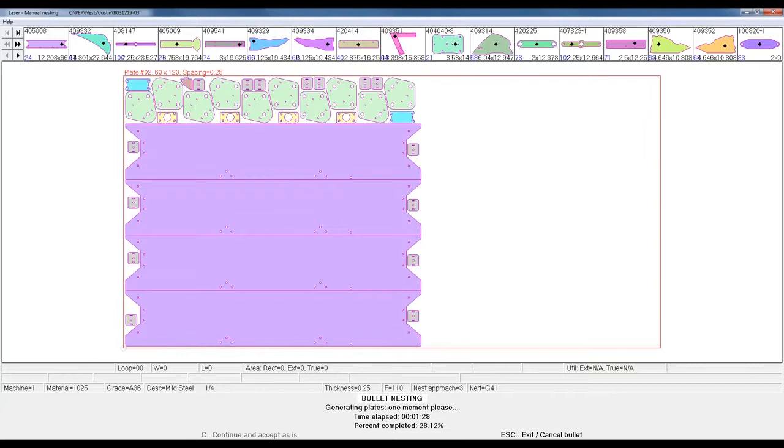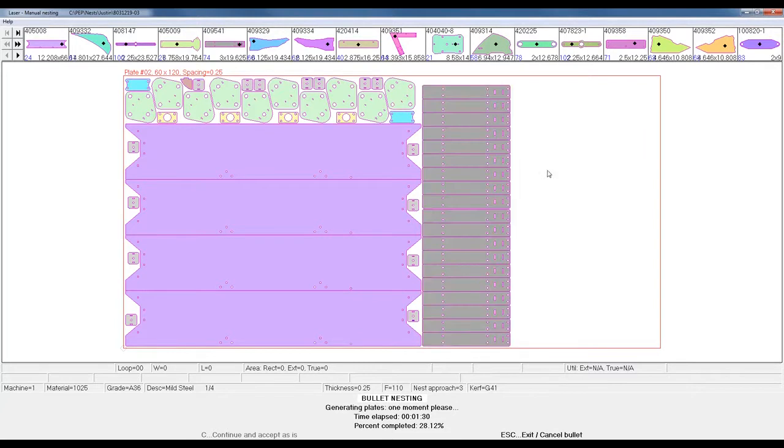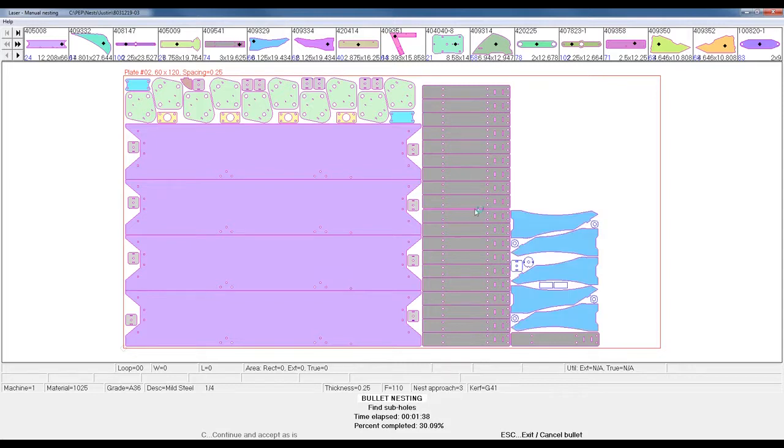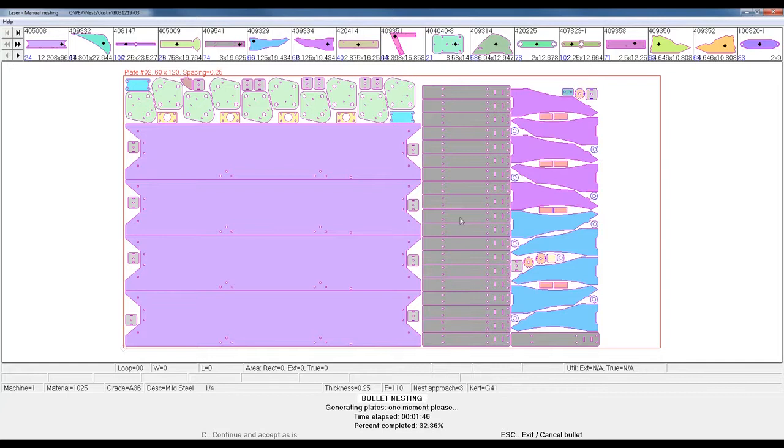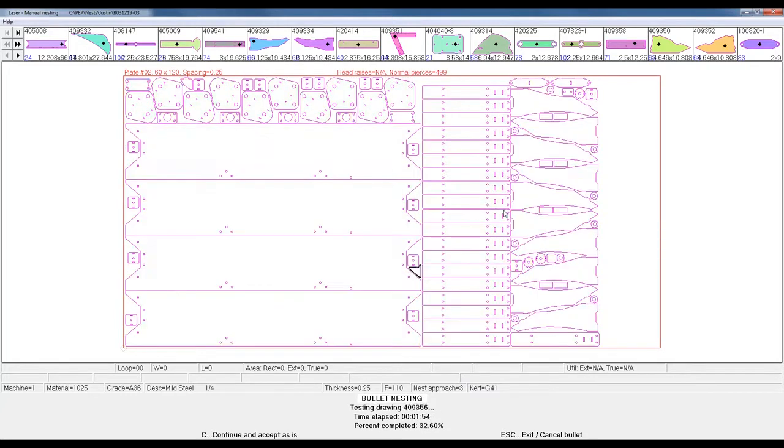So here we've got sheet 2, and it's doing that same thing. It's filling the sheet up, and you can see these dark gray parts also fell within that common line preset defaults for what you would automatically common line cut. The gray parts are a little different because right now there's a preset limit in those defaults of how many to put in a row before we use a fire break. And that fire break is that small little area of metal you can see. If I zoomed in, you'd see it a little bit better, but it's nesting, so I won't.